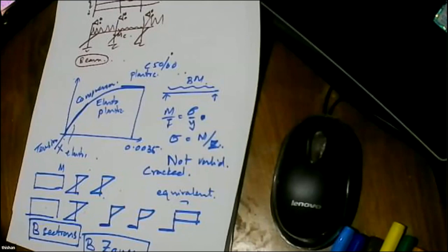Generally, as you all know, the socketing recommended is 1 meter minimum. Otherwise, the diameter of the pile is the socket length. That is the general rule; the general rule is 1 meter minimum. So if it is a 600 millimeter pile, you will socket it 1 meter. If it is a 1200 pile, you will socket 1200 millimeters. If it is a 1500 pile, you will socket 1500 millimeters.